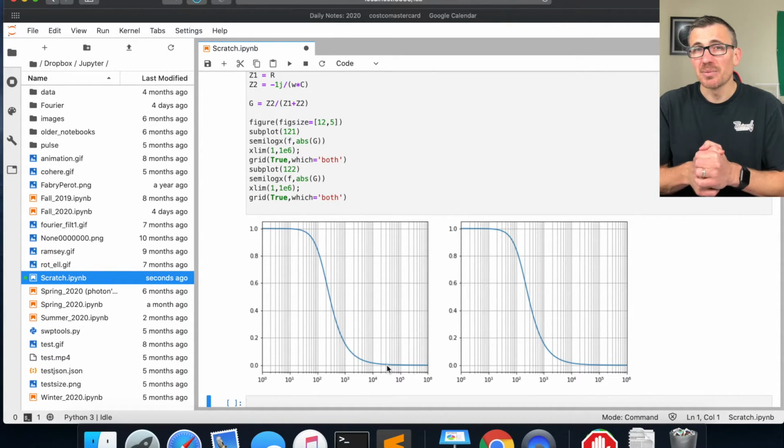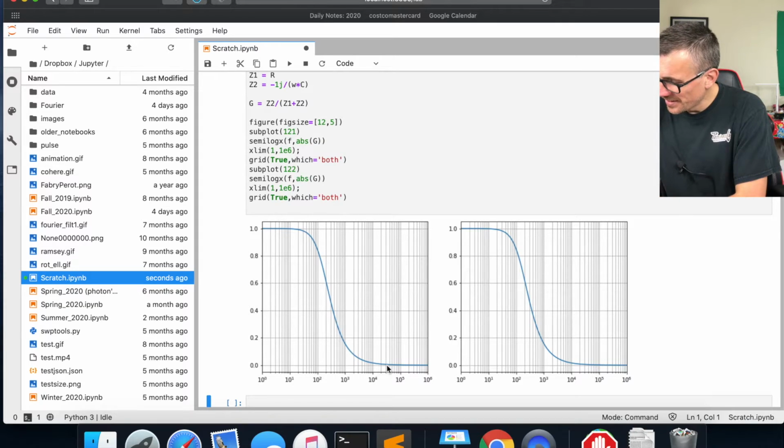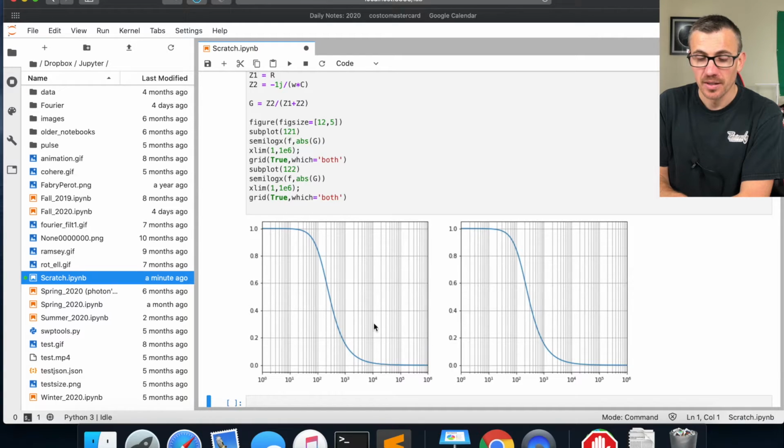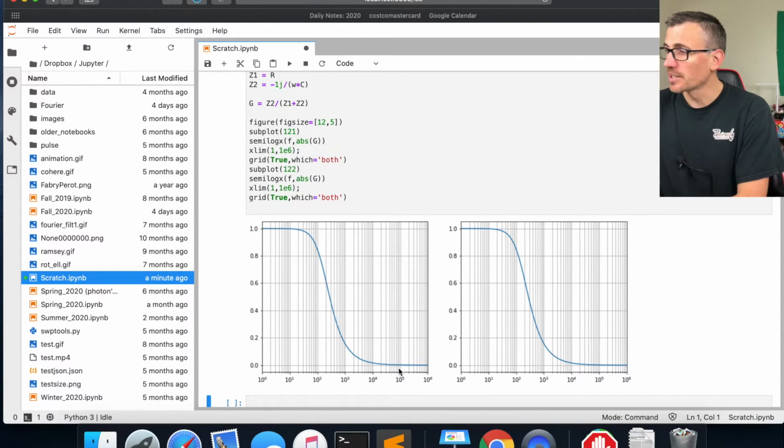Except there's one last thing we want to do. If you can hear it, please ignore my chickens clucking in the background. Now there's one more thing we want to do here. We want to visualize what happens in this region here near the high frequencies. Everything is condensed to a pixel here. But we might be suppressing the 1 megahertz a lot more than the 100 kilohertz. But it's all in 1 pixel the way it's plotted now.